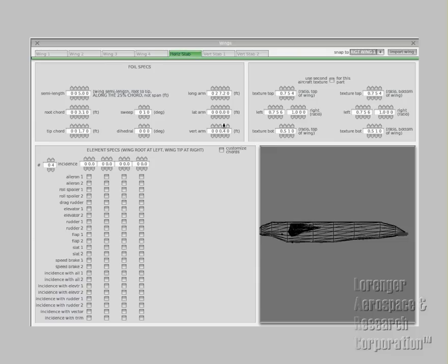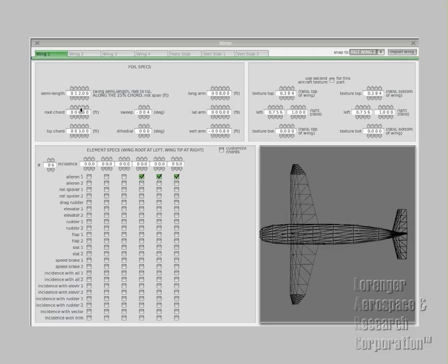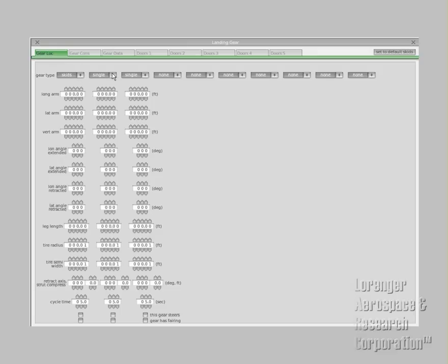What you're going to need to do here is design your plane based off of performance. And right now, if you look, it's a very long aircraft, 28 feet long, and it has a long moment arm. You see where the control surfaces are? Since it has such a long moment arm, you do not need large surfaces because it will actually cause instability issues, and you can overstress the airframe. More on that later. Again, you should know exactly what you're designing before you attempt to do this. I didn't, so you're seeing all the errors as we do it. But you will run into these errors, so bear with us.